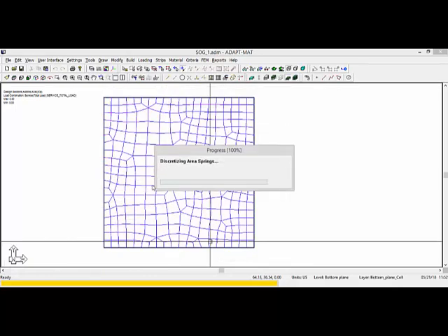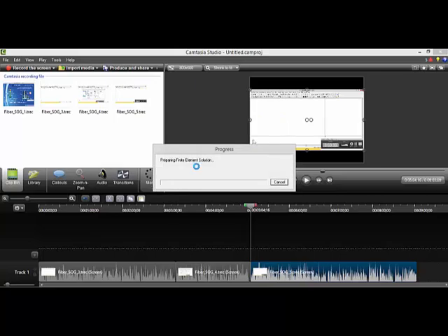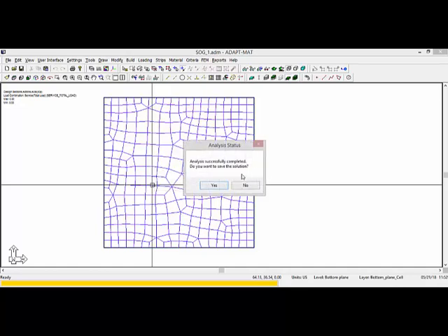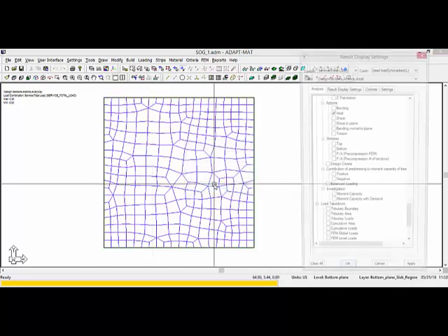We're going to run the analysis for a couple of service and a couple of strength combinations. The service combinations also would not be affected. We're only looking at the strength combinations in this case. So for displacements, we're still looking at a linear elastic response. For strength, we're looking at the nonlinear response for purposes of flexural design.